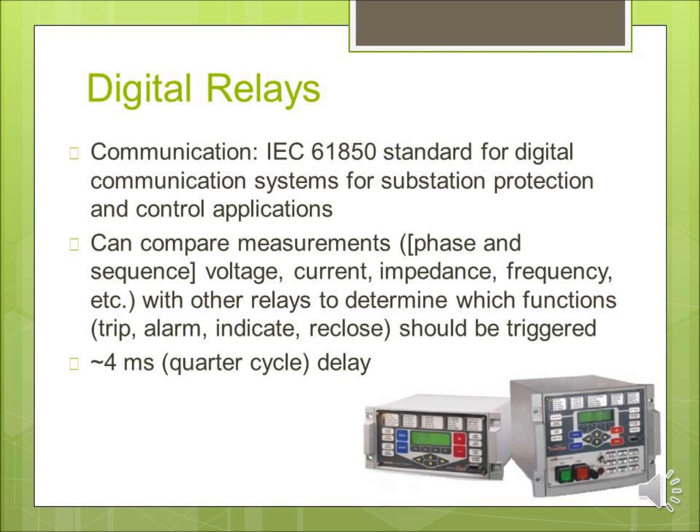They can compare measurements such as phase and sequence voltage, current, impedance, frequency. Digital relays also have a delay of only 4 milliseconds or a quarter cycle, which is also significantly lower than its electromechanical counterpart.